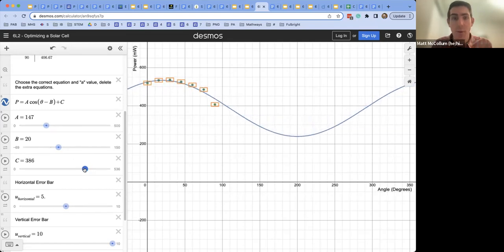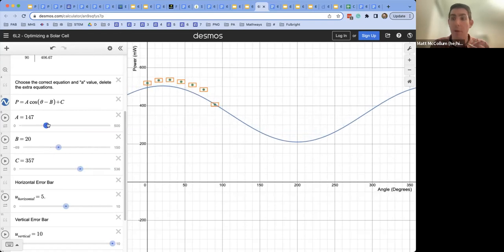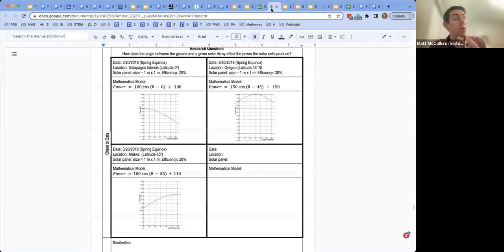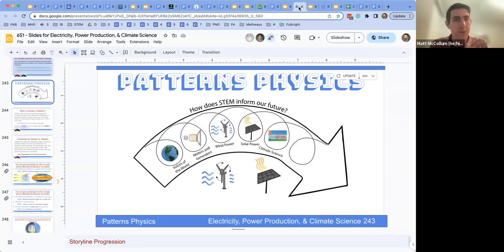The last thing is you want to hook it up to a load, maybe like a resistor or a light bulb. In the supply list, there are something called variable loads. You need to hook those up so that it has something to send the electricity through. Depending on what, the new Vernier sensors have that built in, but if you bought them a few years ago, you need a separate resistor load.